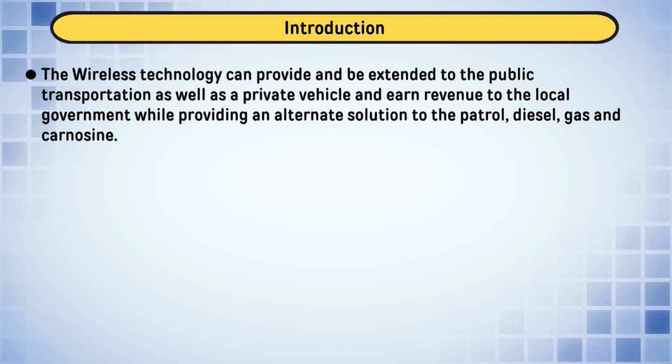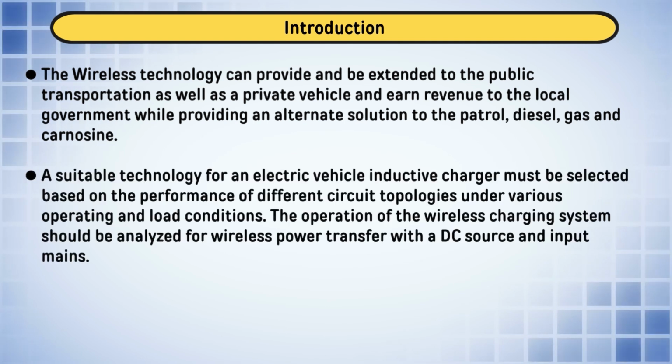If the battery is available, they can inject the power drawn from the battery to the grid to support the grid under peak load demand. However, when the battery is discharged or the SOC of the battery is less than the permissible limit, like it is hitting the lower limit of 20%, these converters can charge the battery by taking power from the grid by regulating voltage and current at the DC bus.